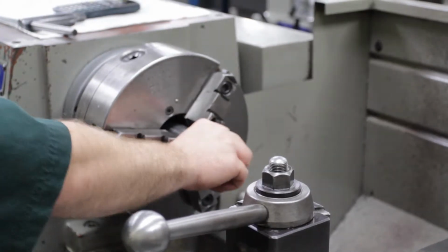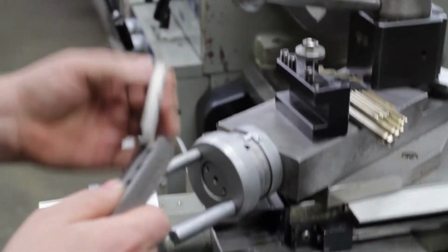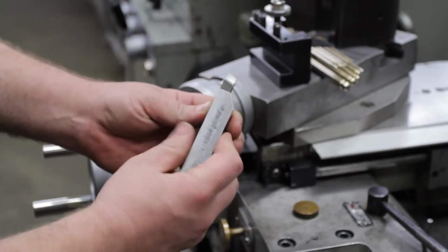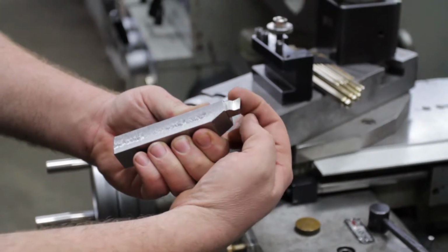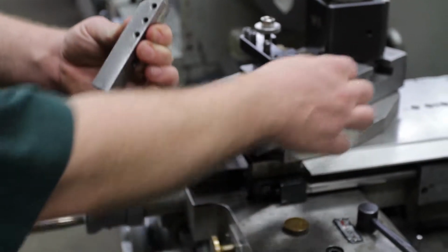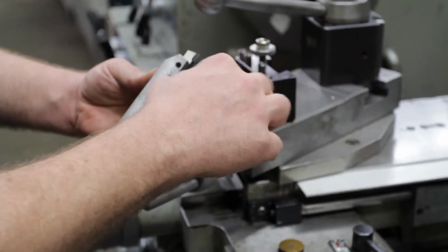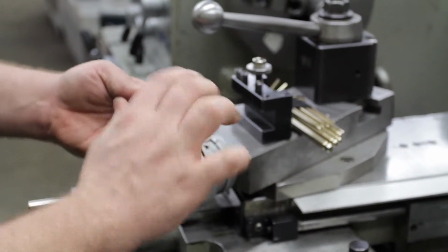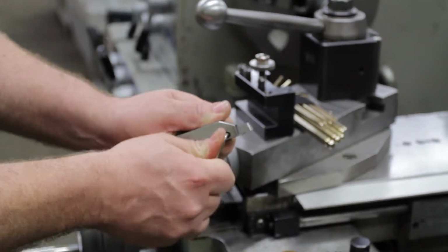After we have our workpiece and our work holding device, we have to set up our cutting tools. Your cutting tool is the one that you ground. The tool holder you made on the milling machine, remember the thicker part of the tool holder is the bottom of it. So we'll put the tool in there with the cutting edge on the upper, this is the top, on the left-hand side. On the bottom side is where the screws are. So you need to find the right Allen wrench. I think it's this one. Yes. And when you tighten up these tool bits, you want to work away from that edge. That edge is very sharp, so you want to pull the wrench towards you and away from the tool.